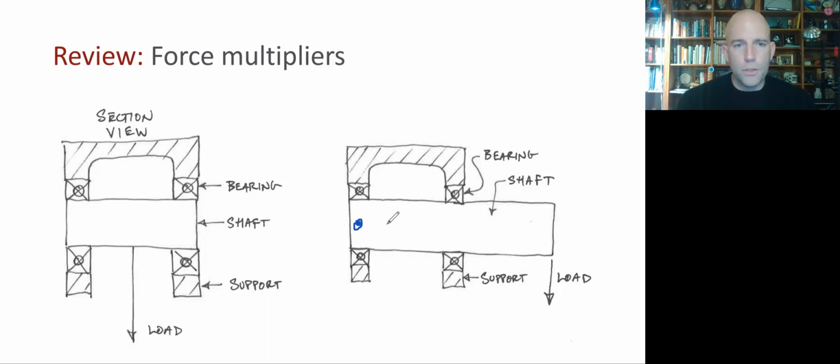This load force has a long lever arm about that point compared to this bearing. So this bearing force will have about half the leverage of this load force. So that is, the reaction force here has to be double the load.